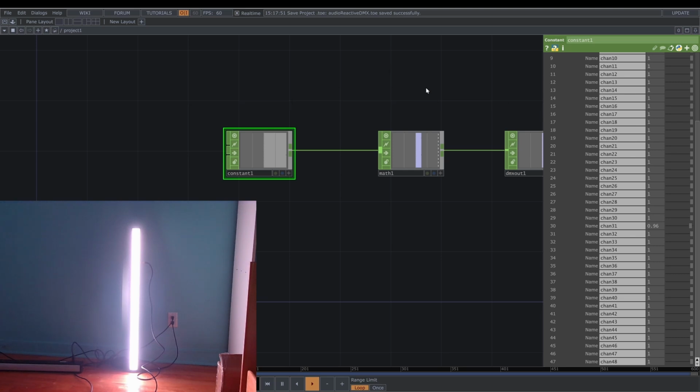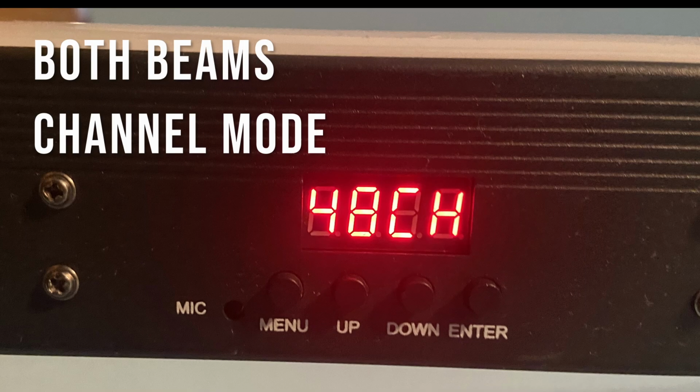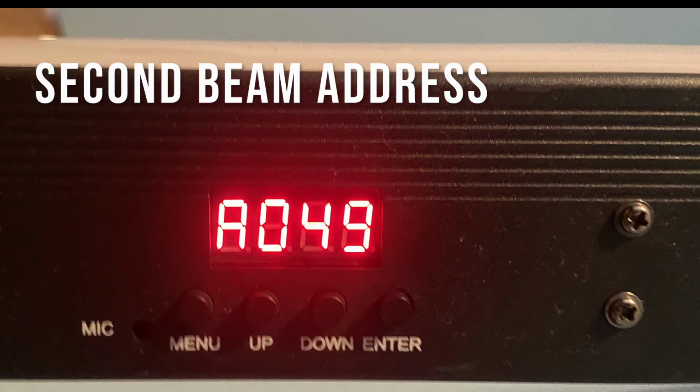You need to know the relationship between the address and the channel. The address means the starting channel. For example, the first one has 48 channels, and I set the address to 001. The next address should be 049, because this is the first channel of each beam.